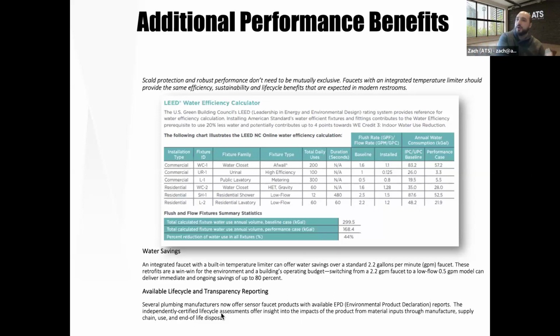You're not doing that all with one valve. Two valves work together to get there, so that you don't have major cavitation. It's the same thing here with our temperature selection. We need two valves to do it properly. We need a valve to make sure it's above a certain temperature, and we need a valve to make sure it's below a certain temperature.